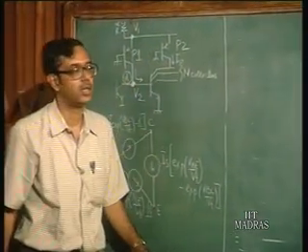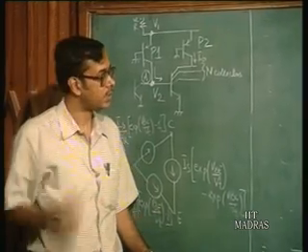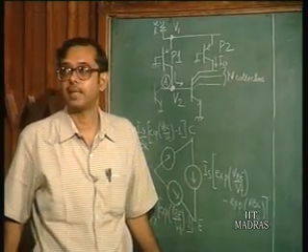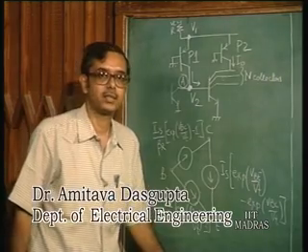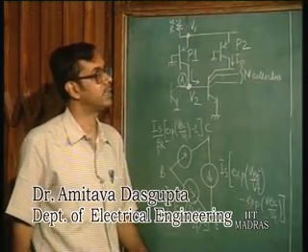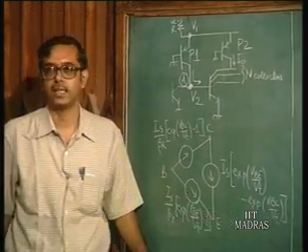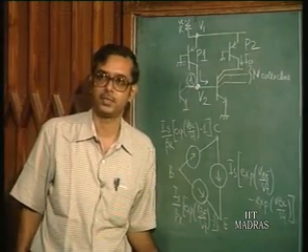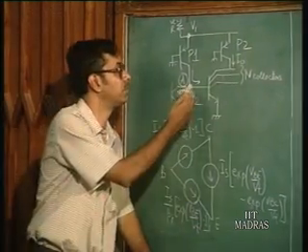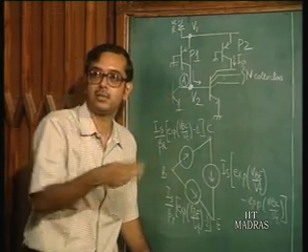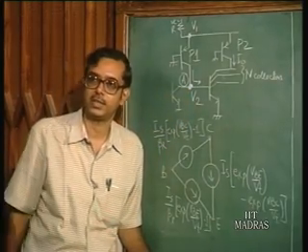Okay. All right. Now, firstly, if we take up the noise margin, that is quite obvious also that the noise margin in an I squared L cell is not going to be too good, because of the fact that the voltage levels are constrained to within 0.2 to 0.7 volts at each node.